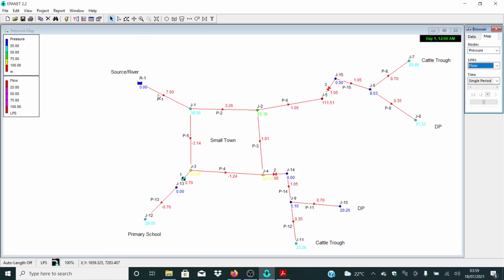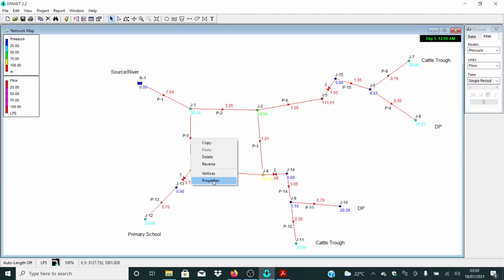At least now our model is okay, but let's ask ourselves a simple question. Now we are having some negative values here. Again, here we are having some negative flows. Remember, this is a flow. To remove these negative flows, we just right click this one, select reverse and run again. You can see now the negative disappeared, and also this one, do the same, reverse and then run. At least now we don't have negative values again.